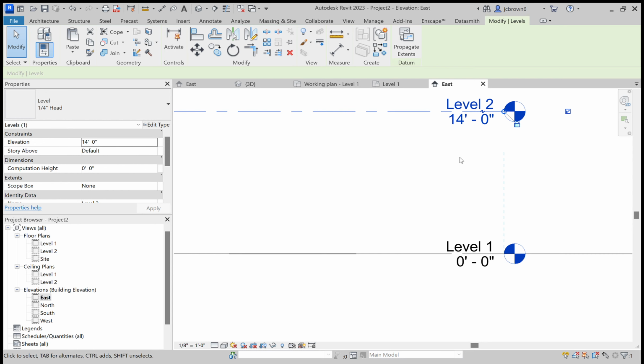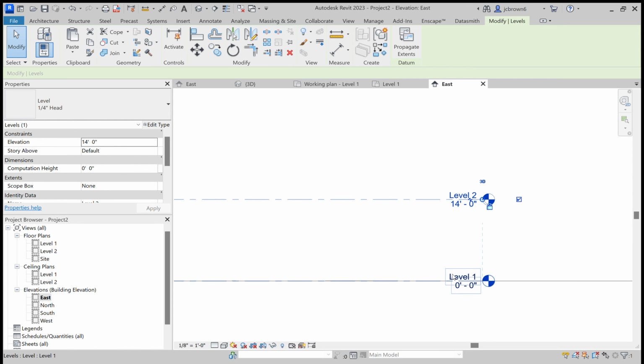13 feet. So you'll create individual files because at the end you'll link your files together, but this will allow you to adjust and create your own Revit file and not have to work in the same Revit file. So establishing who's going to be on level 1, which will be 48, and who will be on level 2, which should be 49, is important when you start your models, because then you'll know who needs to link to who, and they will link appropriately. So please establish that before you start your Revit model with your partner.